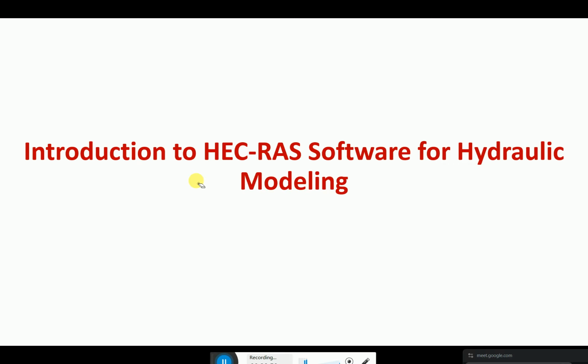So for rainfall modeling and surface runoff modeling, HEC-HMS is good, but for deeper dam break analysis, if you are doing it in HEC-HMS, then it's limited. But in HEC-RAS, it's excellent. And HEC-HMS uses only the modified Puls, and this equation is the Muskingum and lag methods. And HEC-RAS is used for river flow simulation, but the main purpose of HMS is rainfall-runoff modeling. So these are the differences between the two.